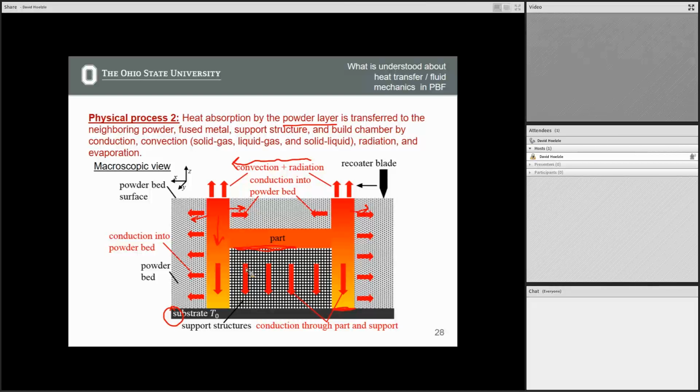Where you can see it, and we won't talk about that idea so much, but with the directed energy deposition methods, like the blown powder, you can pretty easily switch the powder streams that are being blown, and so you can change the material spatially with the directed energy deposition methods. But with powder bed fusion, it's kind of tough.